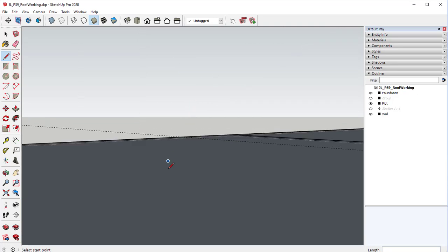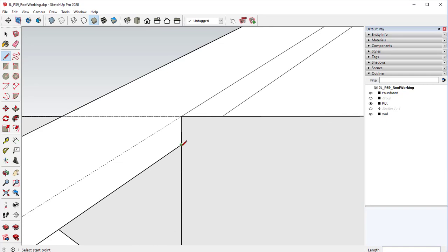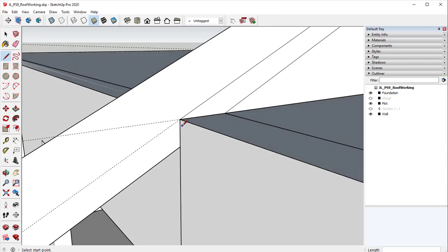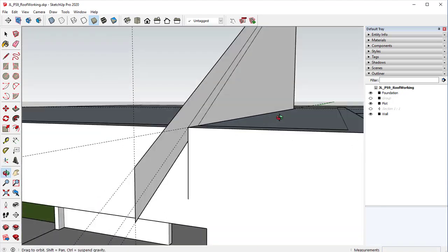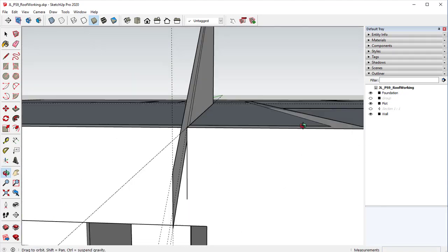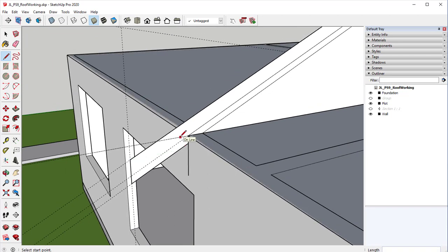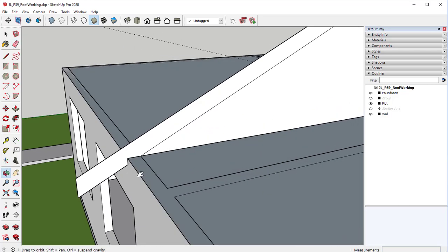If it doesn't, make sure that you do close in this part and this part, and that everything lines up perfectly straight. If it doesn't enclose like that, that could be some of the issues that you had. Okay. Next, we're going to erase all of our guides. If you make a mistake, again, hold down Control, hit Z, and that will undo it.